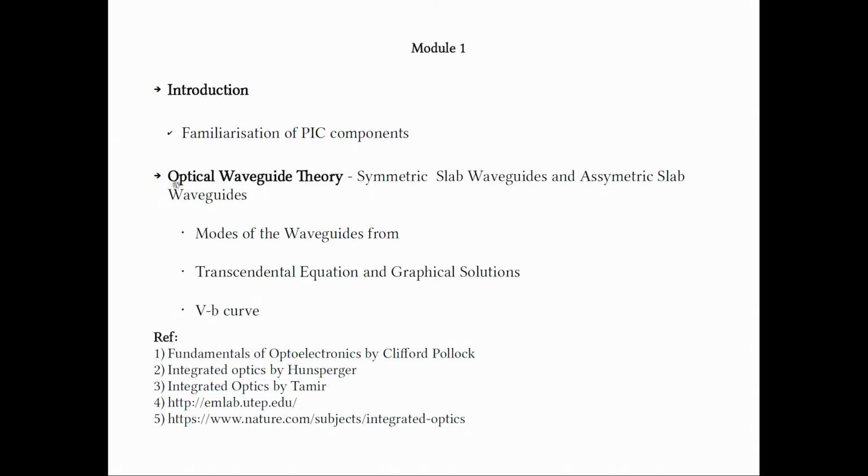So as an example to go deeper into understanding the propagation of light in the waveguides, we took up symmetric slab waveguide first, and used a scalar approach to find out the various modes of the optical waveguide. So we arrived at a transcendental equation, and we look at various methods to handle that and interpret that more importantly, and finally in terms of the design we end up in what can be called as a VB curve.